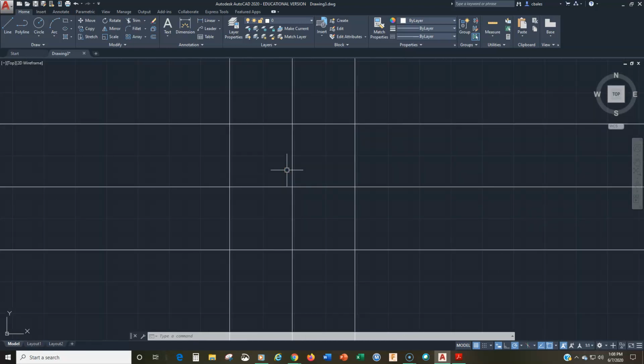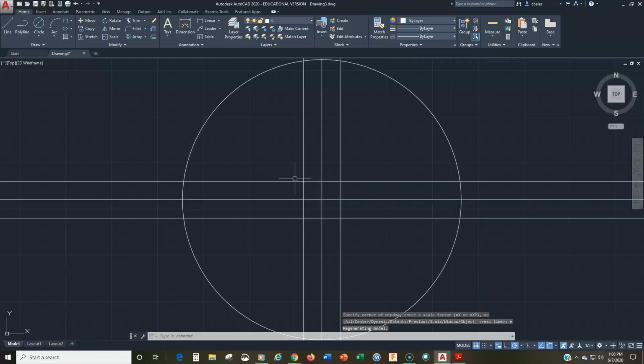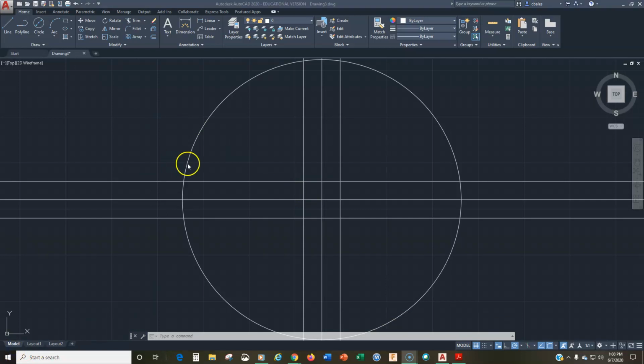All right. Now we want to put the circle in there. So we'll start with the center one, diameter 76, and we're going to go to Circle, Center Diameter, and we choose that, and we go 76. Whoops. All right, so what happened there?